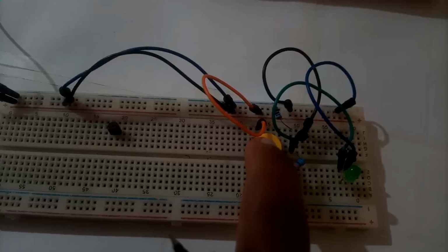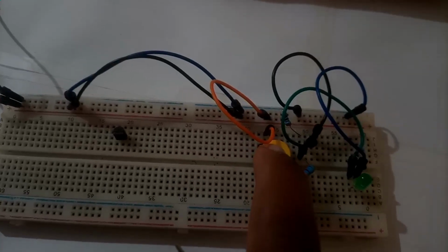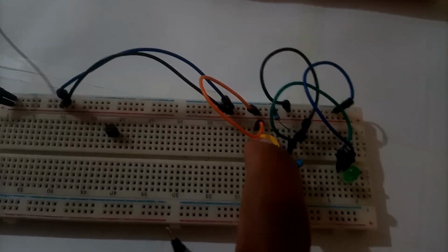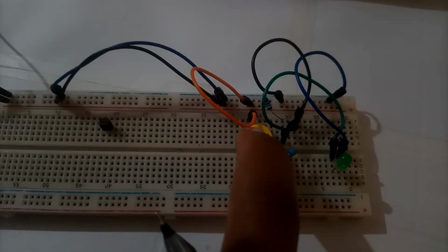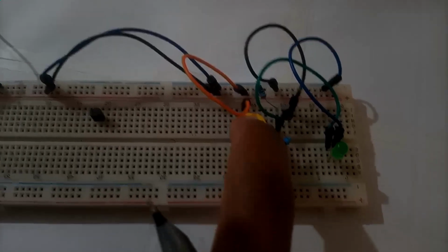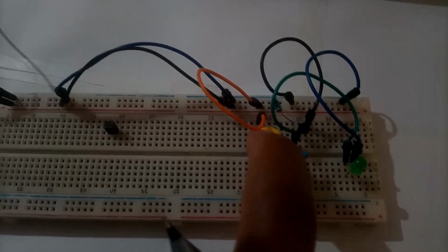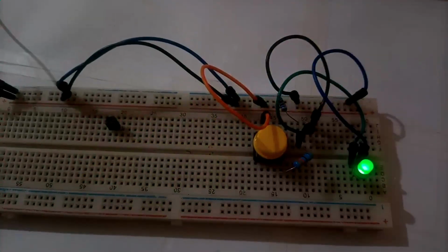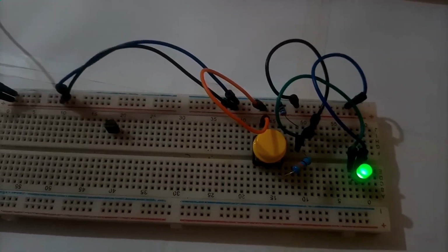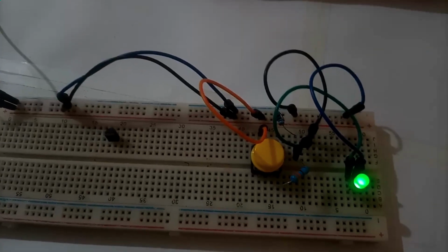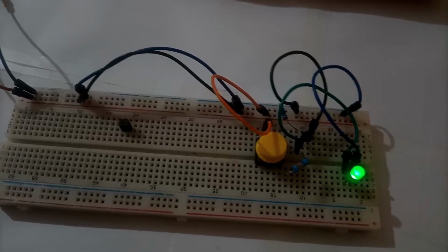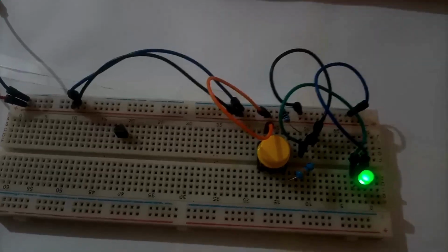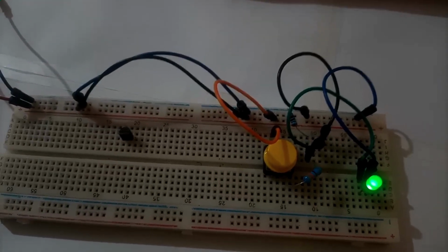It's doing the inverse. Assuming this is the input, and clicking down is inputting, it's allowing the current. It's not even assuming, by clicking this, I'm completing the circuit. And by completing the circuit, weirdly enough, the LED does not light up. And by releasing, it does light up. So yeah, it's kind of an inverter, and this is very important. It's called a NOT gate.